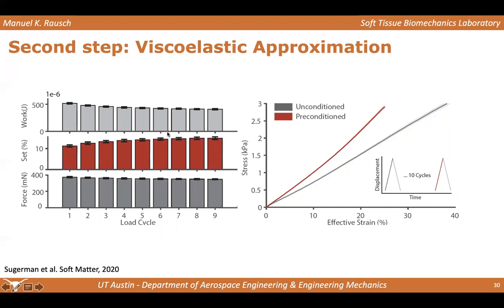Something else we were interested in was to see how this material actually changes over repeated loading. So we loaded this over 10 cycles, and we looked at things like the hysteresis work, basically the area under the curve, how does this change, as well as the peak force. And we see that there's an initial change, and then it equilibrates toward a pretty repeatable behavior. But interestingly, as we do so, the material actually changes its characteristic quite a bit.